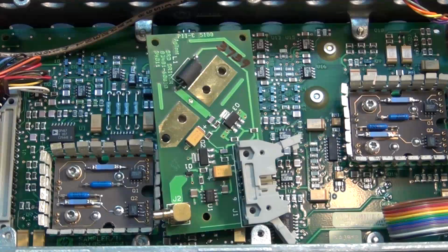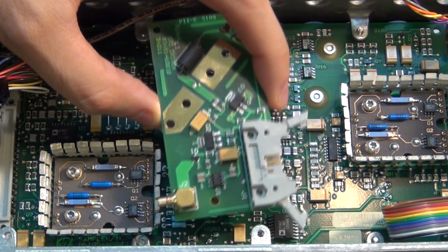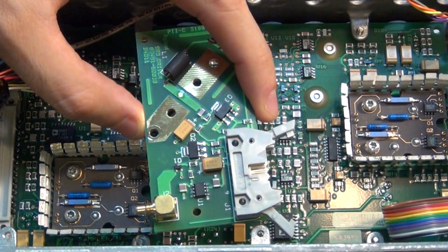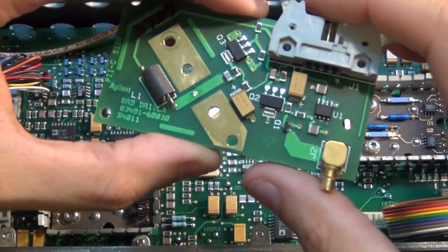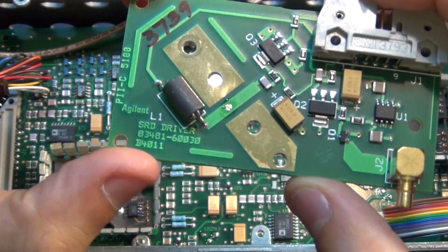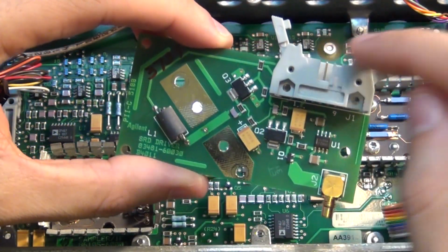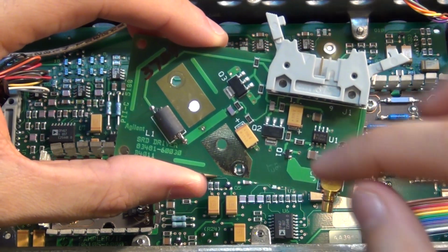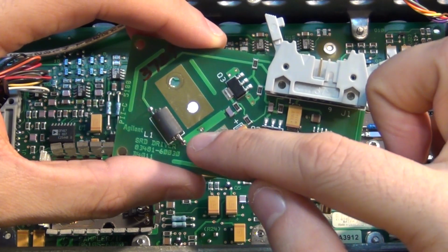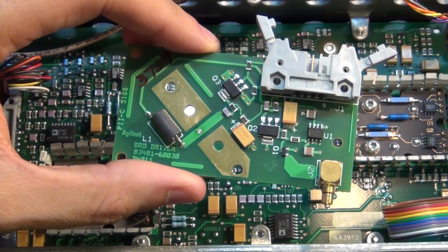Well, now check this out. Here's another example of why the Keysight engineers just don't care about cost. I love that. Look at this. If you remember, I talked about the pulse shaping and the sampling, and I said it's most likely a step recovery diode driver, and in fact that's exactly what it is. I didn't even notice. It says SRD driver here, which is a step recovery diode driver. And these are high power amplifiers to receive the trigger signal, amplify it to a very large peak-to-peak amplitude, and then feed that through this little pin into the board onto the other side to the step recovery module, creating the pulses.